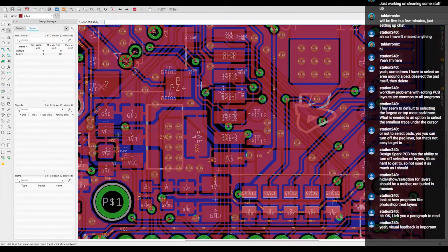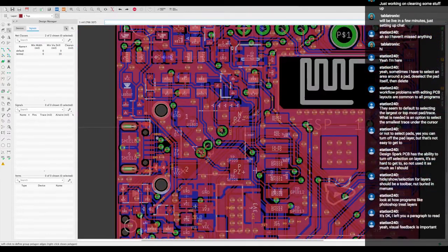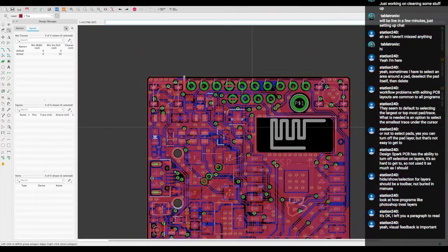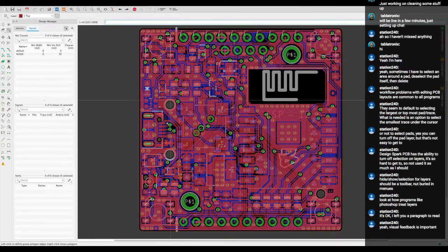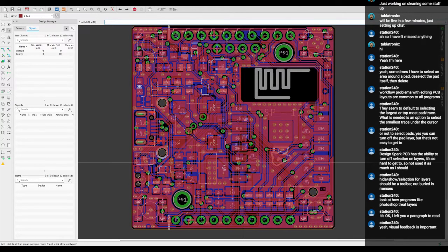All right, I think I am almost done. So that's really the only changes I made. I had to add a fix because my piezo was clicking when the ESP restarts. It outputs a 200 millisecond, uh, microsecond? I don't remember, I have to look it up. But when I was playing with it, I noticed a real short burst, I think it was 200 microseconds, when it initializes the GPIOs, they go high or something like that.